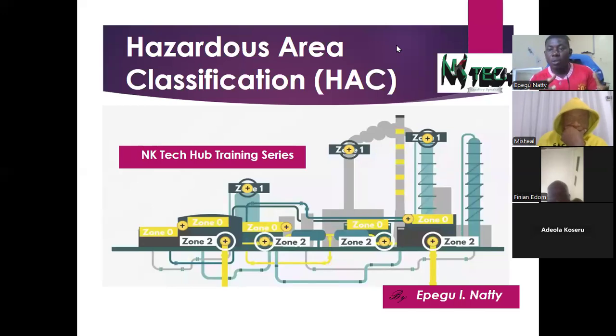So what you're going there to do is just to operate, and then you focus on the other barriers, like the safety instrumented systems, the normal control barriers that you have in your plant, using your control valves to ensure that you control so that nothing happens, and also the operator experience in trying to prevent accidents. So those are the areas operators actually try to manage.